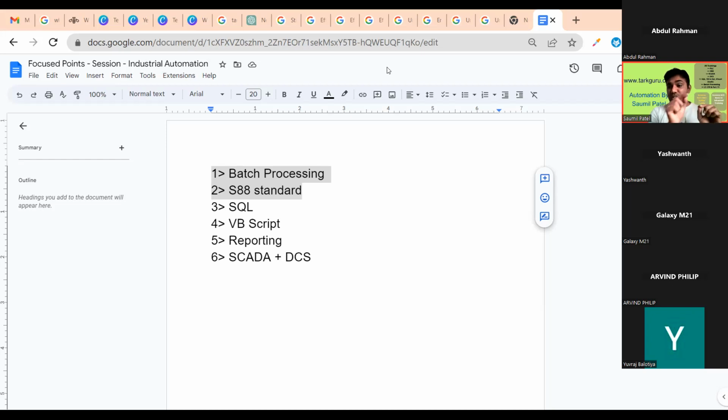So these are the processes you need to follow inside the phase. So phase is nothing but the term which is very much mandatory to use when you are programming with the S88 standard. If you do it like the procedural method, then there are no such terms, right? But you are doing it by yourself, like start the pump, start the valves, whatever it is, right? It is an unstructured programming way.